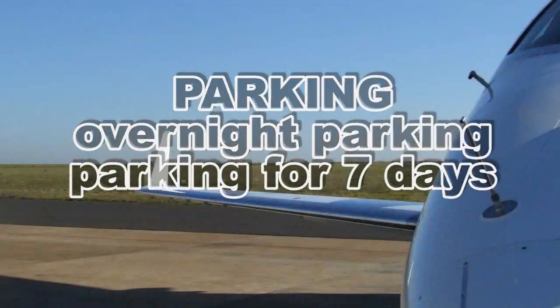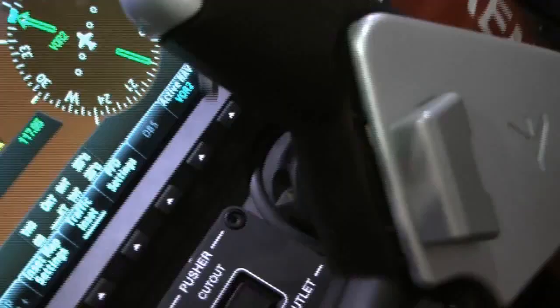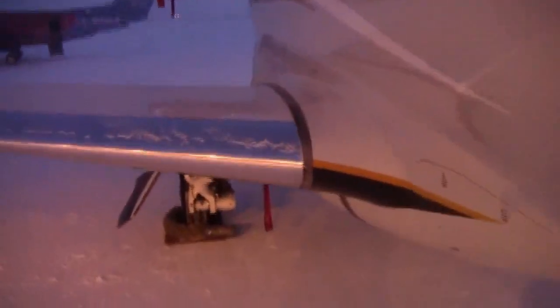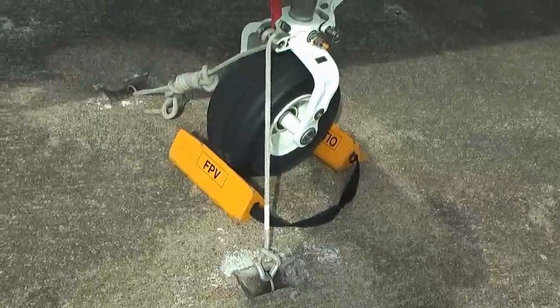Parking. Emergency parking brake. Set. Flaps. Up. Gust lock pin. Install. Doors. Close. Landing gear safety pins. As required. Wheel chock. Install. Covers. Install. Mooring. As required.